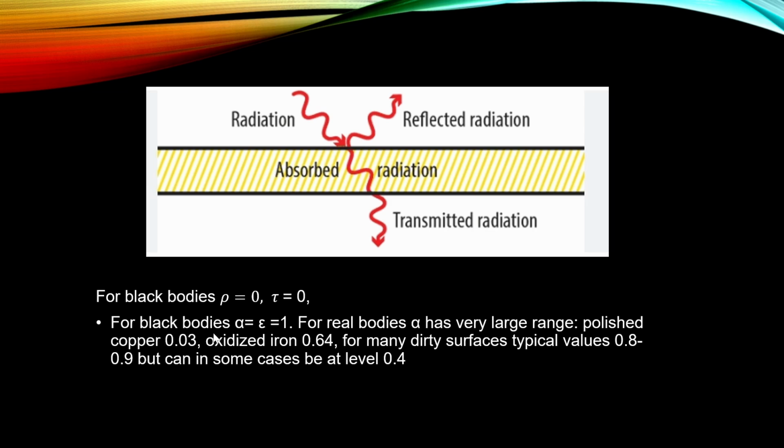But for typical materials this absorption coefficient is around 0.4 to 0.8. And typically in industrial applications we have some deposition layer on the surface, and for that kind of dirty surface the absorption coefficient is typically in the range 0.8 to 0.9, but in some cases it can be even 0.4.